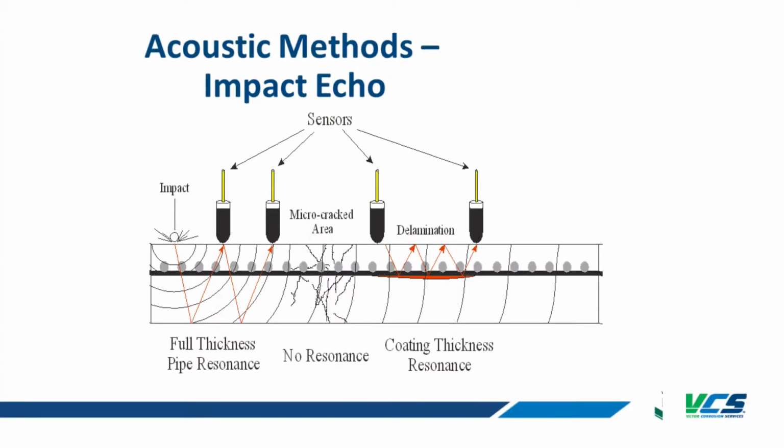We just use sensors. So we make an impact, and then we monitor with sensors the vibration of that stress signal in the slab. And we can effectively, based on the frequency of vibration, identify the thickness of this slab. And if there's a delam causing that stress wave to vibrate at a higher frequency, then we can identify that there's some delamination or incipient cracking that's occurring.